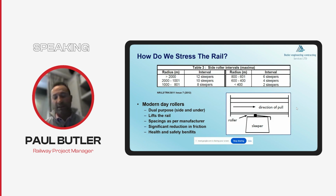As with the length of free rail, the frequency of rollers also increases as your radius decreases. As you can see here from table 3, if you've got a radius of 1,000 to 800 meters, you need a side roller every 8 sleepers. And you can see from the right of the table, as you start getting tighter, the amount of side rollers that you need increases significantly. So this is one of the main considerations you need to have of how many rollers you might need and how big your stressing site should be based on this.